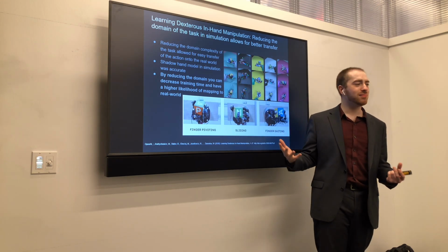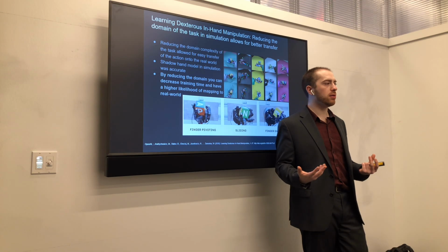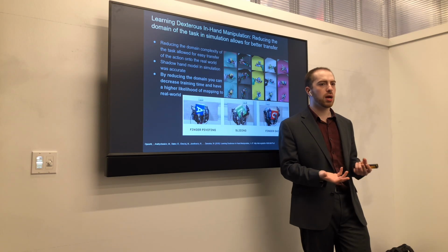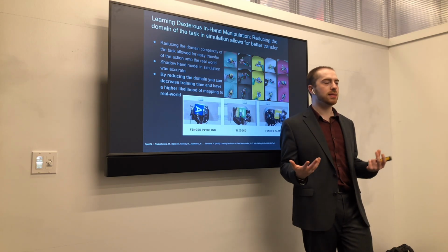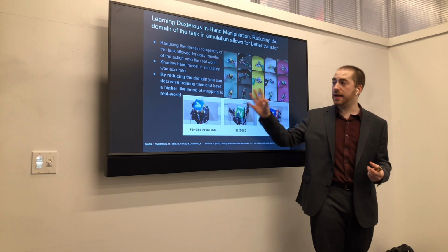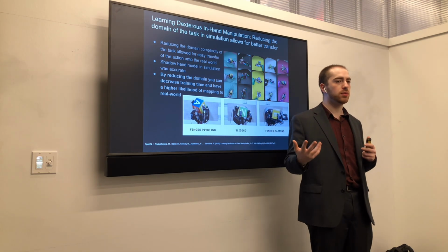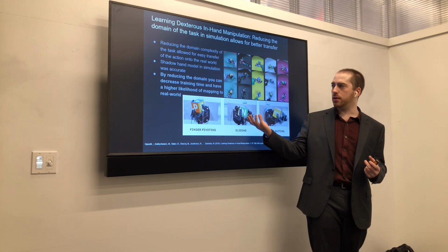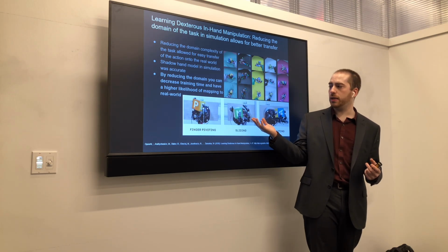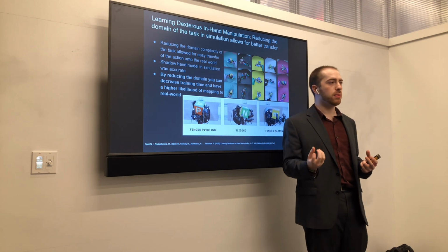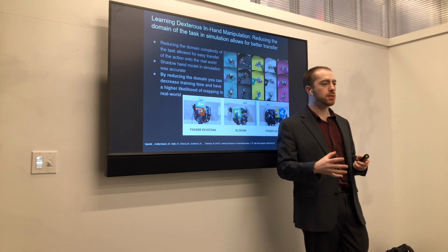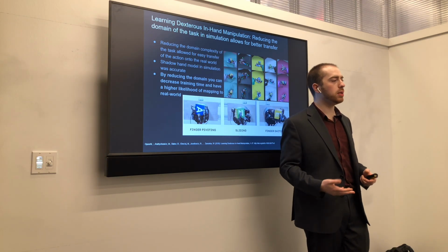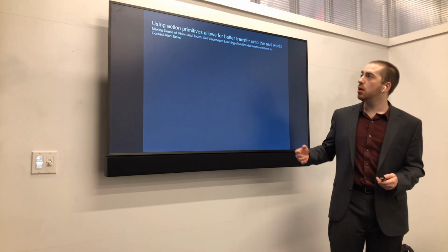But what I want to point out is that constraining the problem the way they did doesn't necessarily generalize to lots of different problems. They're just moving a cube in the hand. They're just looking at whether or not the correct face is showing. This isn't a stacking task, but it is a nice example of how we might formulate different sim to real problems, randomizing the colors of the meshes, randomizing the different types of faces you would be looking at, and then actually manipulating an object, and perhaps I'll talk about a modular system. We could use this as a particular module in a much more complex solution.